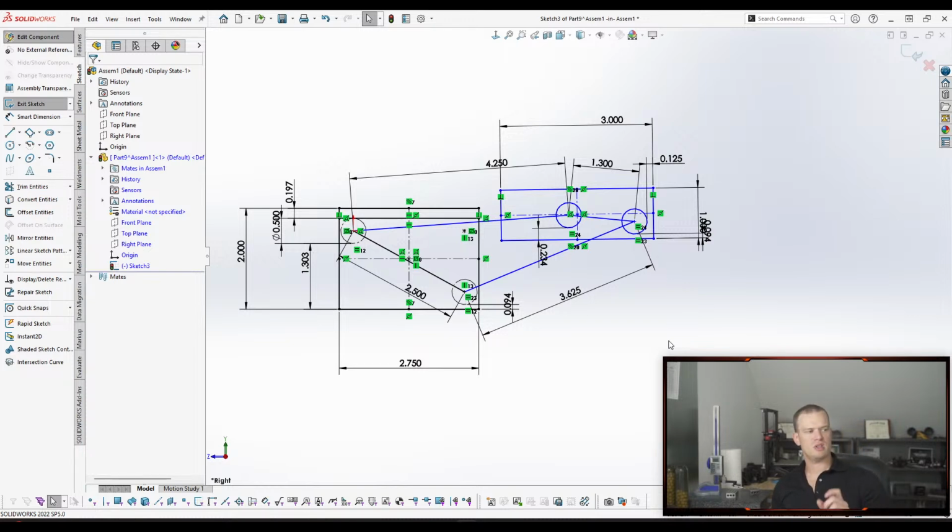If you're trying to make a model and you want it to change based on just changing a few dimensions, skeleton sketch modeling, especially if it's an assembly, where you have more than one part and you have to pass those relationships against each other, watch our video on skeleton sketch, top-down modeling, because that's the best way to do it. So there's two different modeling methodologies.